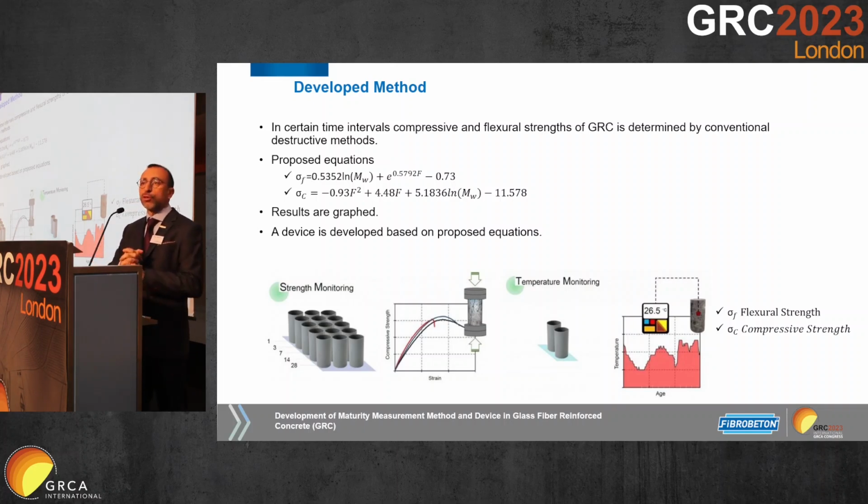But for doing that in a daily environment, we cannot make these tests each day. Therefore, we are trying to get the best knowledge from that mix design. And as you may see from this screen, there are two main equations popping up from these test results, actually, one for the flexural, one for the compressive values, and the calculated maturity index.